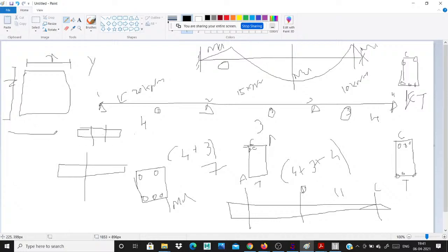For example, you provide the stirrups, right? In the center portion, the stirrup spacing is high, more than 200 mm or something, right? But at the corner, sometimes you provide the stirrup spacing as 160 mm. Why? Anyone? The center spacing is 200. Correct.